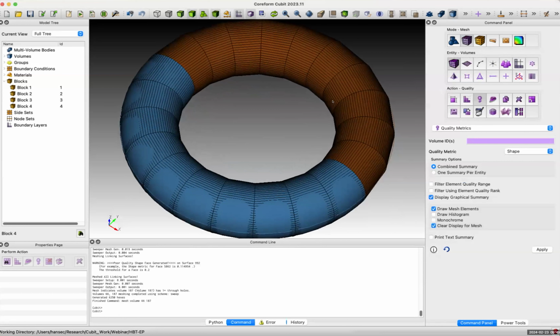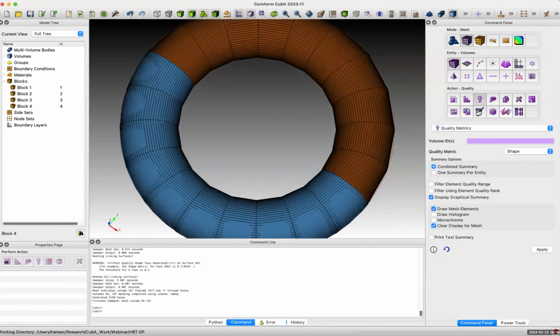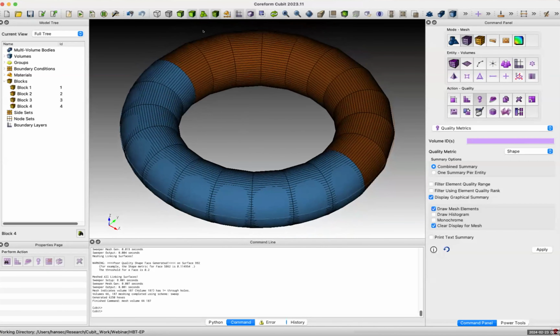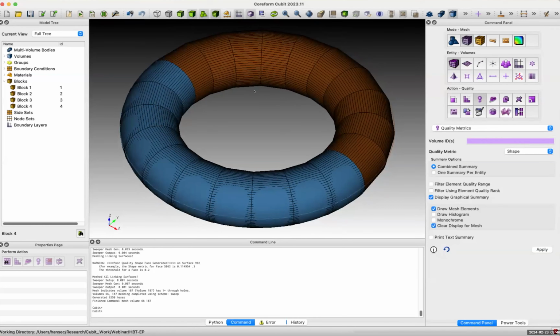In this case, you can see it looks a little bit chunky, but what I can use is a higher order mesh export. So I can use like a hex 27 type to provide curved elements in this case, which will allow us to better capture the geometry. And you can see by providing this sort of swept structure, the mesh is more or less matching the direction of the geometry and also the direction of the underlying plasma structure.